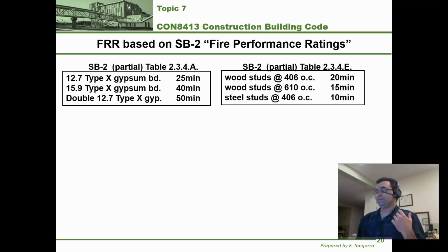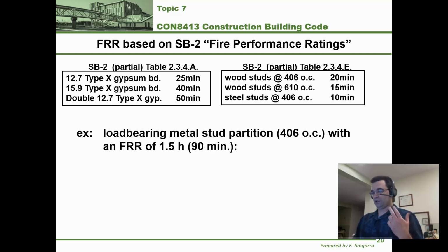Let's try another one. What about this example here, where you're told to figure out a load-bearing metal stud partition with that spacing and a fire resistance rating of 1.5 hours, 90 minutes. We can do that. We're allowed to do that. Let's try that. I see, by looking at tables 2.3.4a and 2.3.4e, this combination...